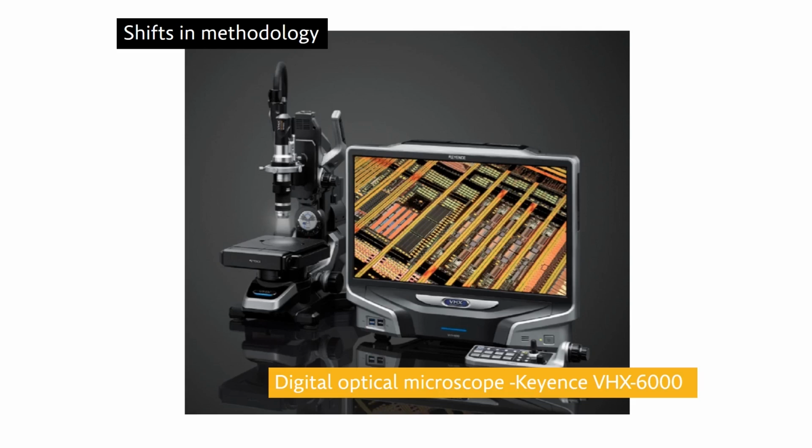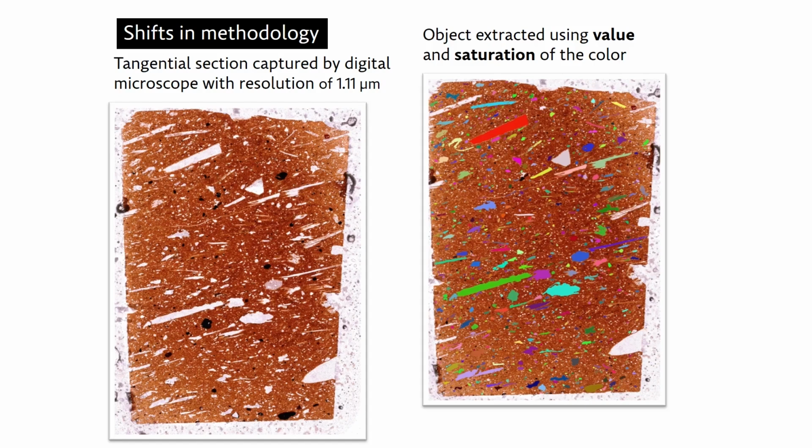During the third experimental collection, we used Keyence's digital microscope instead of a petrographic microscope. This significantly speeded up the whole analysis process and increased the quality of the recorded images. The entire area of the thin section is recorded by a sequence of images captured at magnification 200 times, which are automatically stitched together.